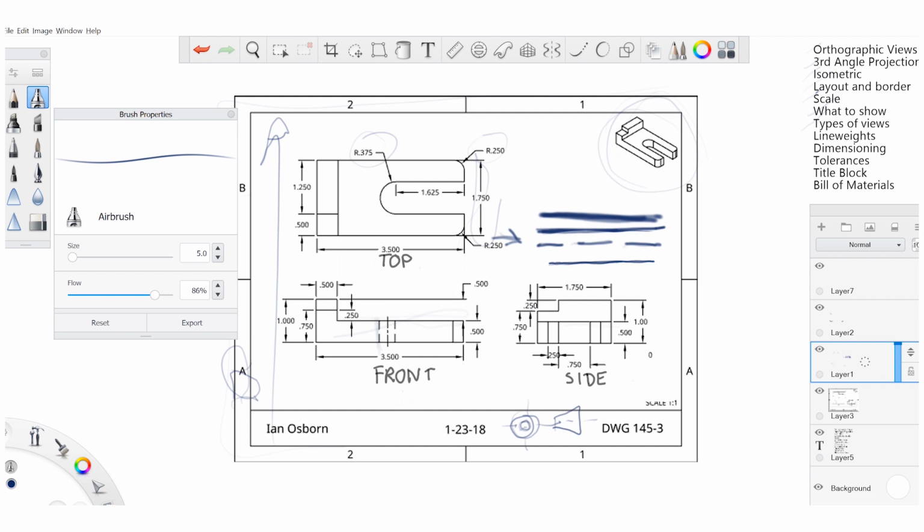Things can get confusing if you do use all the same line weights, so please keep this sort of stuff in mind. Okay, in terms of dimensioning, you can see on this product that there are dimensions absolutely everywhere. Whilst we do want to include all the dimensions that are important to our model, we do not want anything that is irrelevant or doubled up.